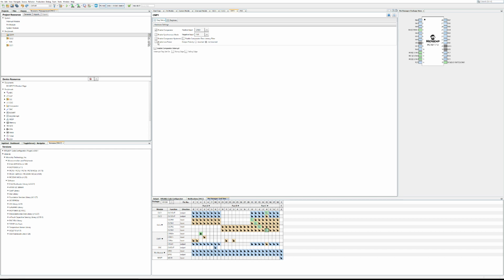There is a low power mode for the comparators, which slows them down, but makes them use a lot less power. I generally don't bother with that because they draw quite little power anyway, but if you're working on a battery operated application or such, then yeah, it can be nice. Especially in terms of what we're talking about here, where we're using the hardware peripherals without leveraging the CPU. You can put the CPU in sleep, and this whole part can be extremely low power, which means with the logic cells you can use them for some very basic smarts to your device even while it's off.